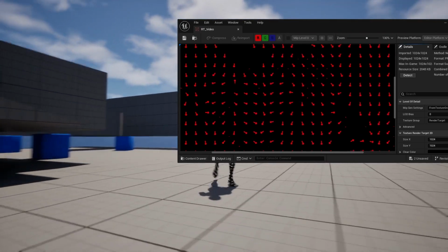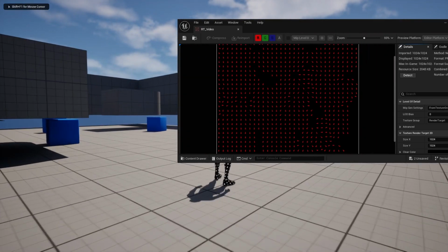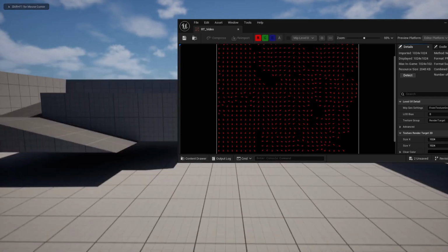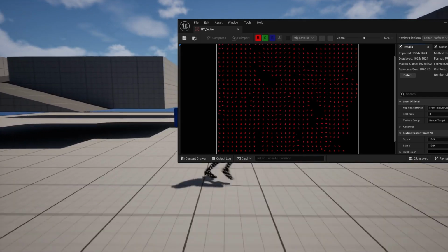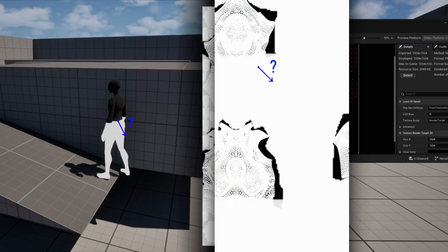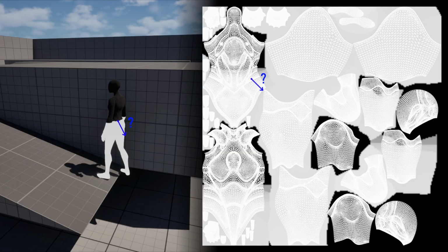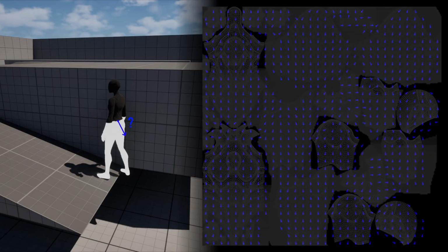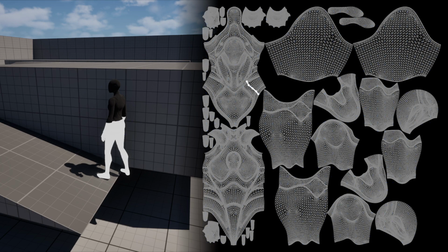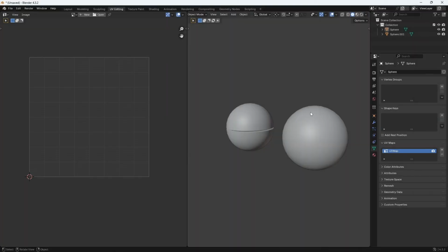Neat. So say if we want to do some kind of fluid simulation on the skeletal mesh in 2D, or at least perform some form of advection in 2D, that correlates to a direction in world space, like gravity, we can do that. But it turns out that's just the tip of the iceberg. Eventually, you'll cross UV boundaries. And at this point, to correlate with the 3D surface in world space, what's advected in 2D needs to somehow jump to the appropriate UV coordinate when crossing a boundary. And there are two cases to consider.